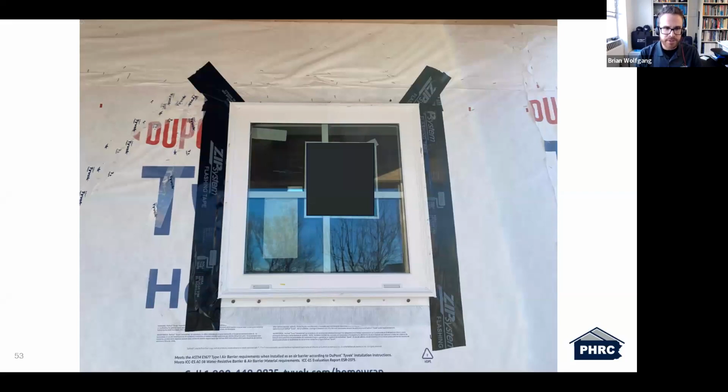You are often going to see mixing and matching of products. And I'm not going to say what is and isn't approved because I always want to point you to the manufacturer. But what I want to say is make sure that the subcontractors that are involved in the installation of the water-resistant barrier and all the flashing details know if you're expecting that a certain product is going to be used to complete a flashing detail.